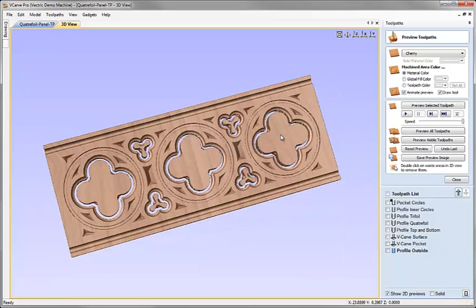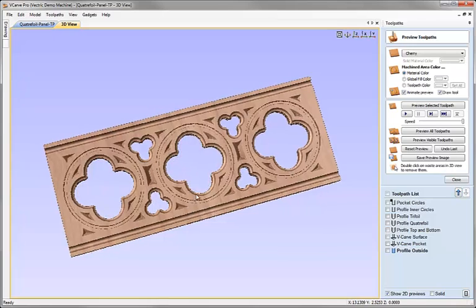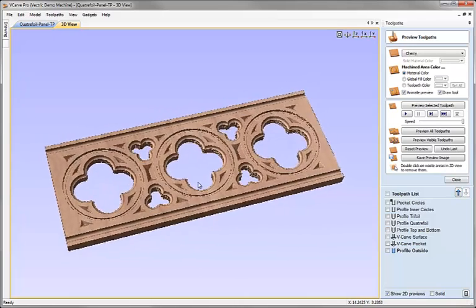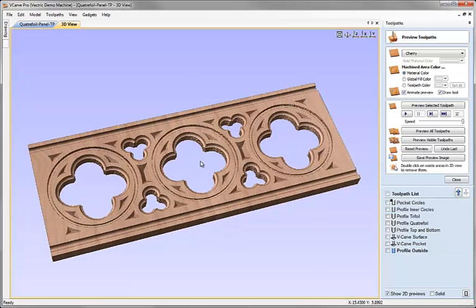So I just put the mouse on that area and double click with it in order to erase that from the 3D view. So I can go over all these pieces that we'd get rid of, and now I have a way of visualizing my part really nicely as a virtual shaded object. And it's even possible to save this image that we can see in the 3D view by clicking on the button here to save preview image.